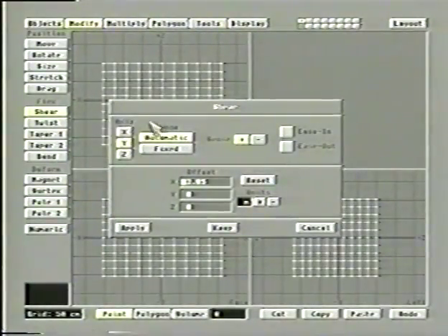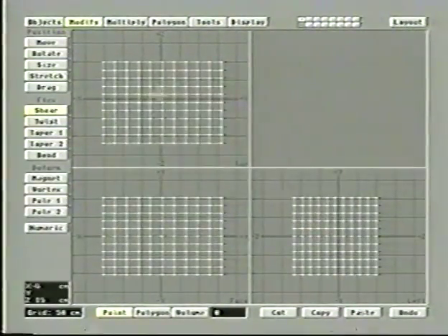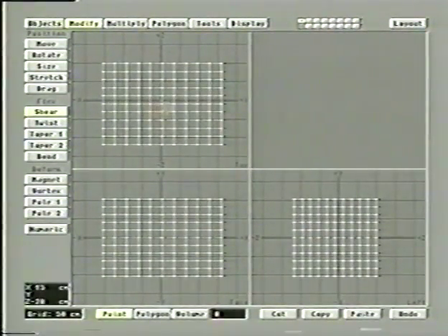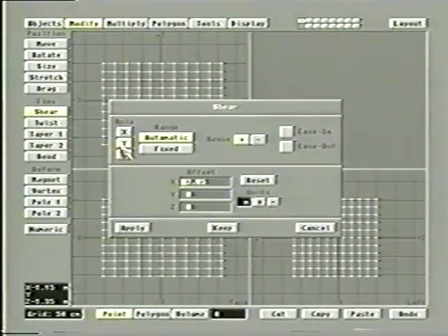And you'll notice there's a few things that are set here, such as which axis you're picking. And in this case, I was clicking on the top here. So right now, we're really going on the Y-axis. And you see that's what's selected. Now, one thing about these numeric requesters is when you perform an operation, they remember what operation you did, and they show you the results of the last operation you performed. So because I clicked there and dragged it a little bit, it shows me that we're on the Y-axis.